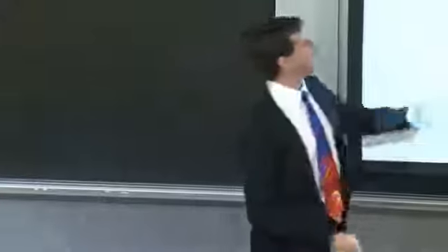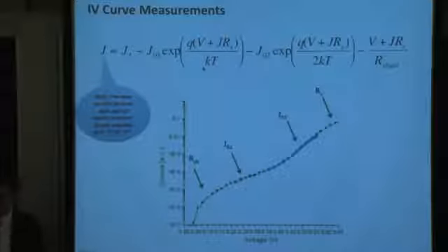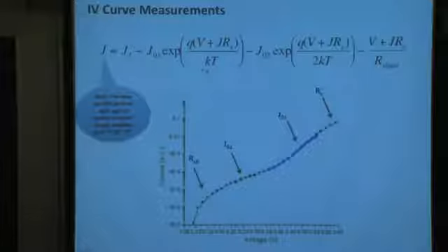The 1 and the 2, the ideality factor, to show more precisely, it's the number that comes before the kT for each of these. That's called the ideality factor. It's typically expressed as n sub 1 or n sub 2. In this case, I just substituted it straight out for a 1 and a 2. Those numbers aren't always 1 and 2. As a matter of fact, especially the J01, the bulk recombination current, depending on where the defect levels lie, it can be somewhere between, say, a 1.1 and a 1.4, typically.